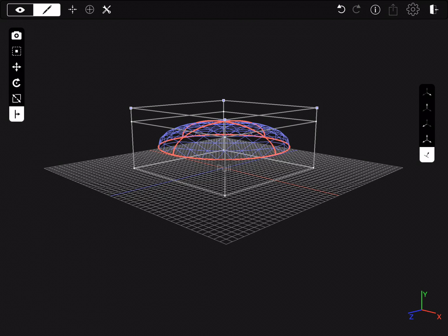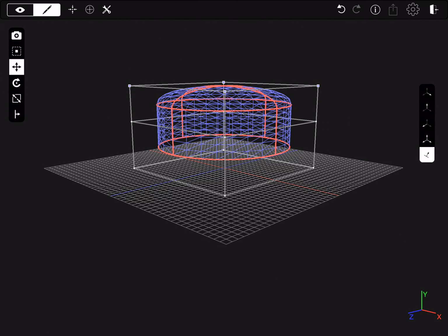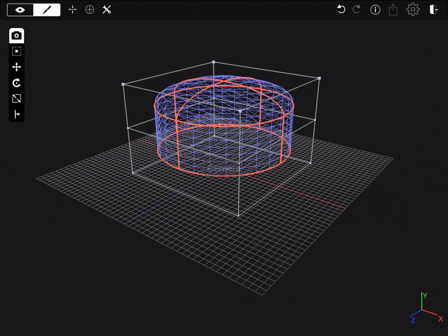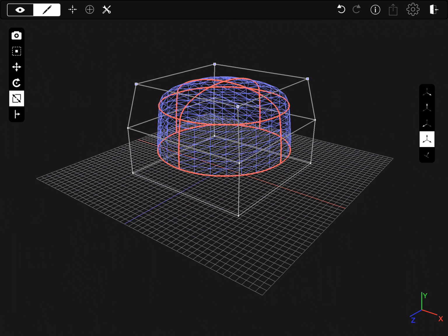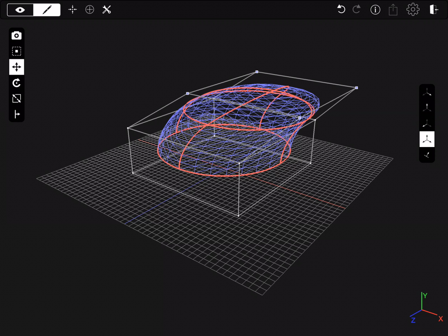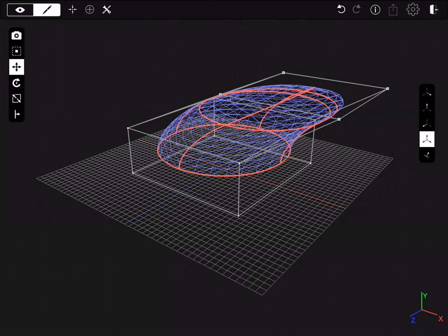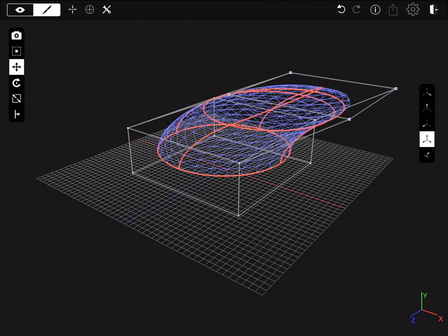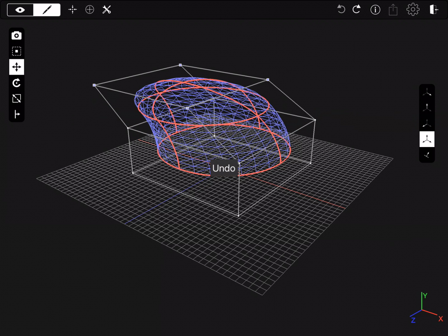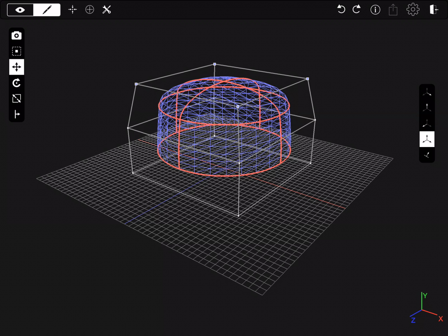So you can see here, I'm just taking a model and extending it using the pull feature in 3D space and creating a curved surface by simply manipulating the control cage vertices. So by me moving this control cage around, the underlying surface will actually reach out and try to touch the control cage points or vertices, and it allows me really simple but complete control over the process of 3D modeling that would normally be very difficult to do without this kind of stuff.